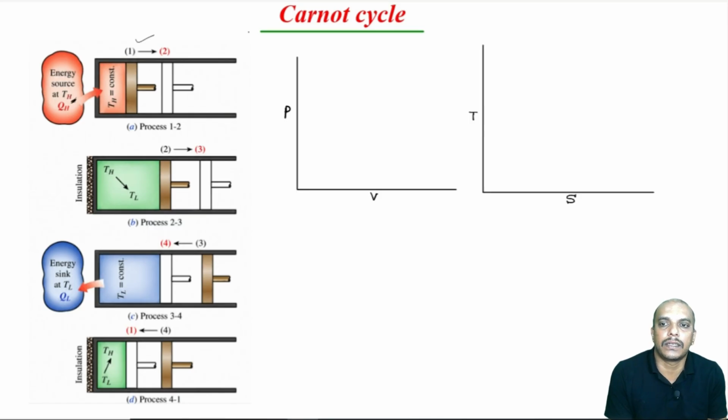Now, it is obvious that heat transfer occurs only when there is a temperature difference, but there is an irreversibility which we talked about in basic thermodynamics. The temperature difference is also an irreversibility. So, whenever there is a temperature difference, there will be losses. If you assume that the temperature difference is very small between the source from which we are taking the heat and the air, then only we can say that there is negligible energy loss or negligible irreversibilities.